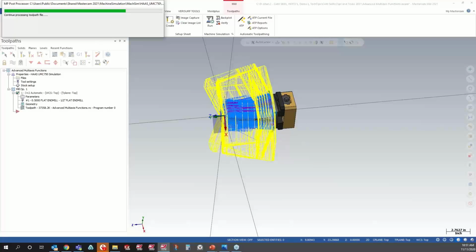If you need a spacer block, like I tell you on this part, I would have needed a spacer underneath that fixture to make sure I'm going to clear the table on rotation. It gives you a lot better idea of what the toolpath is going to look like. Backplot, you know, the tool's moving around the part. Machine simulation, it's actually parts moving and the tool is in the spindle. Definitely appreciate it.